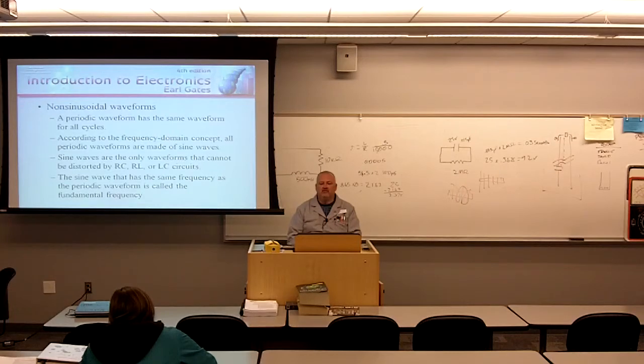Now, according to the frequency domain concept, all periodic waveforms are made of sine waves. Just different combinations of sine waves added together. Sine waves are the only waveforms that cannot be distorted by RC, RL, or LC circuits. So what that's saying is when we feed it through these circuits, it's not going to distort it.